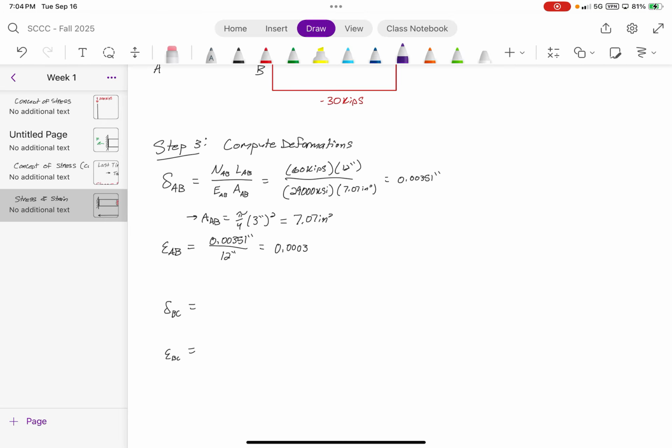I have no idea if that's right, because my solutions are based off of an entirely different material. But your procedure looks good. Just keep in mind the direction that this deformation is occurring. Is this going to be in compression or tension? Well, it was really negative, so compression. Right, so you would want to express this in terms of negative values.